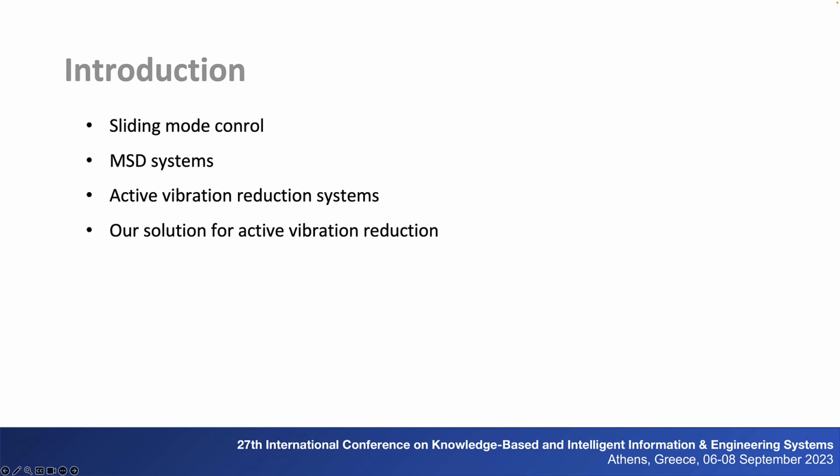The exponential reaching law is a technique used to ensure that the system reaches the sliding surface in a finite time. This is achieved by introducing a term in the sliding mode control law that drives the system towards the sliding surface at an exponential rate.